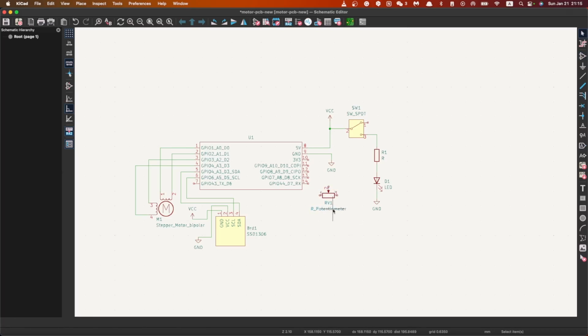So to be aware, if we directly connect VCC to the potentiometer, then to ground, there's no analog signal we can control. That's because the voltage between those two pins of the potentiometer will always be the voltage between VCC and GND. So what we need to create here is a voltage divider. We need another resistor to split that voltage between VCC and GND. So add R, another resistor.